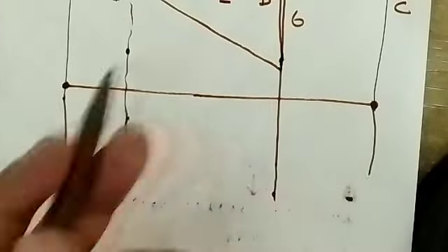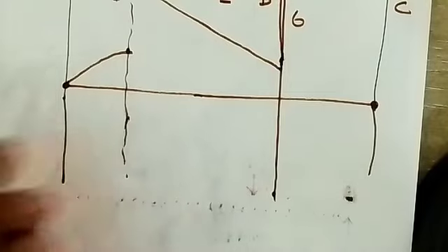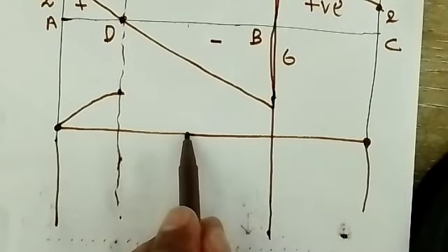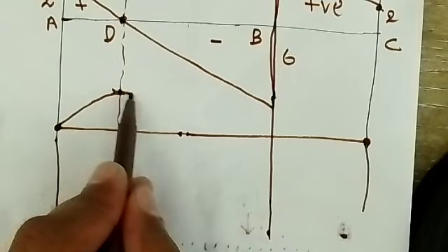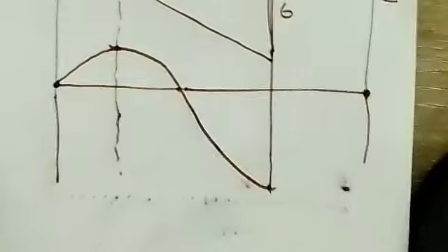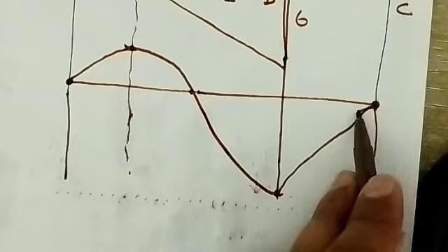So throughout the beam there is the UDL, which means that while you're finding the bending moment, you get force into distance, and the distance power is 2, right? It means that the curve for the bending moment will be an inverted parabola, right? So it is like this, okay? And here at 2 meter the shear force is becoming 0. So let's say this is 4, so it will be 2 here, right? So the shear force is like this, right? For A to B and B to C, again it is an inverted parabola, right?